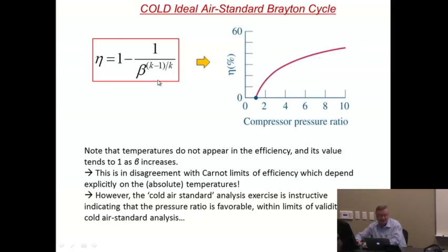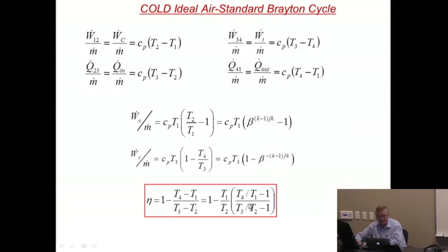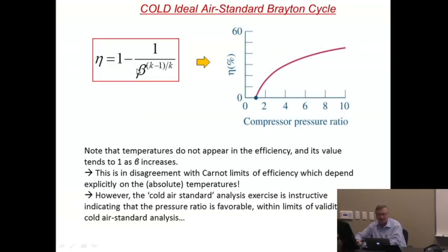Of course, it did enter the previous equation. Here, this is very clearly an expression of Carnot, but it's a fact that these temperatures are uniquely related to this compression ratio. That is a bit strange, and it's really due to this extremely simplifying assumption we made that Cp and Cv are not temperature dependent.